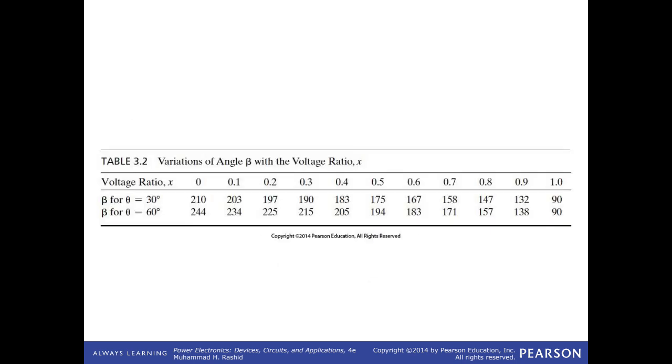And also we have seen that continuous current mode and the discontinuous current mode is also a function of E, the opposite voltage, and also a function of L over R. If L over R is higher, or E is a lower value, it's a continuous current.